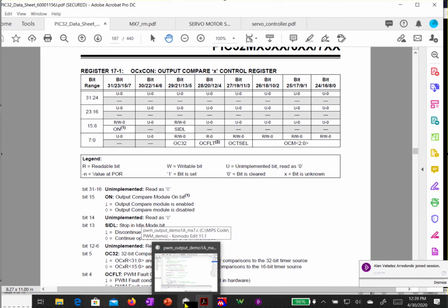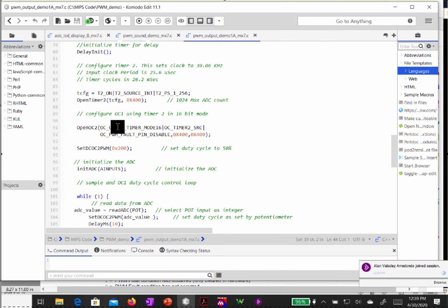So it's basically a 16-bit value with one individual bit set. And so as I OR all of these together, the bits that I intend to be 1 will all be set at 1, the others will be set at 0. Because 0 ORed with 1, the result is going to be 1. So if any of these have a bit set and I OR them all together, then I set the individual bits as desired.